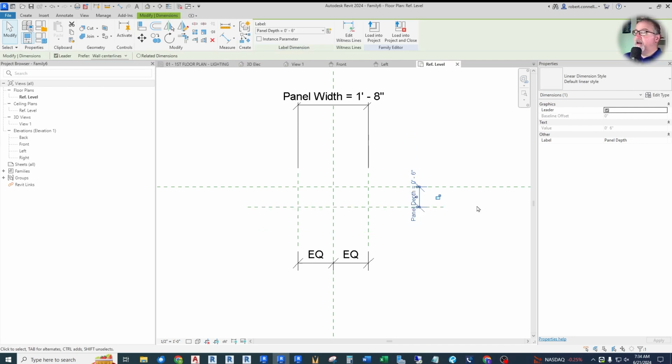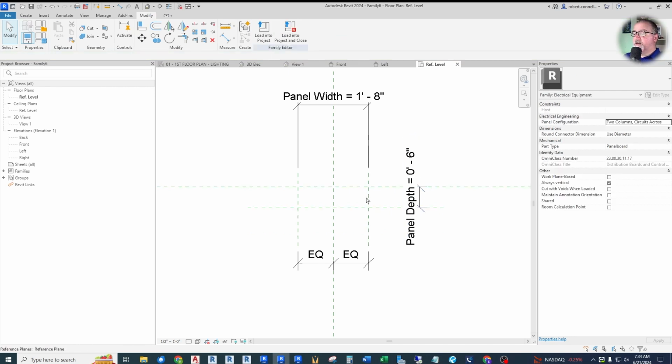Now we're drawing a surface panel board in this case. We're going to treat that line as the mounting surface. It won't be hosted to that surface, which means we can move it anywhere we want. And it doesn't require a 3D architectural background. That's the basics of our panel. We don't need a height because we're not doing a 3-dimensional panel.